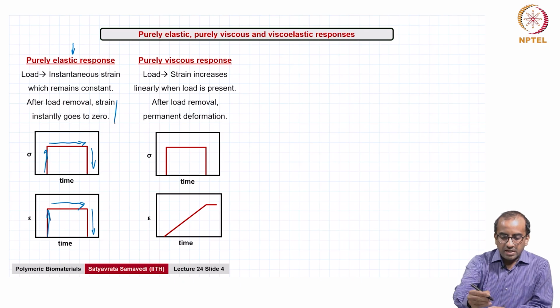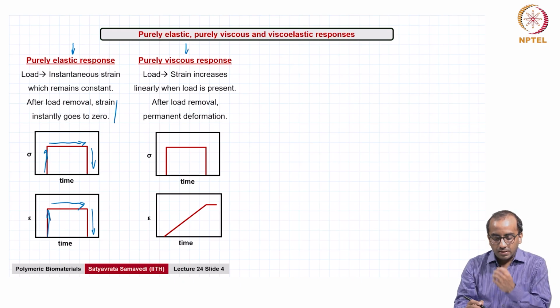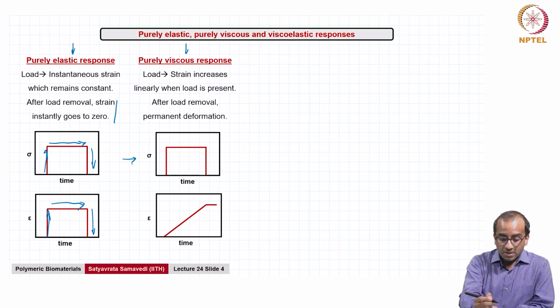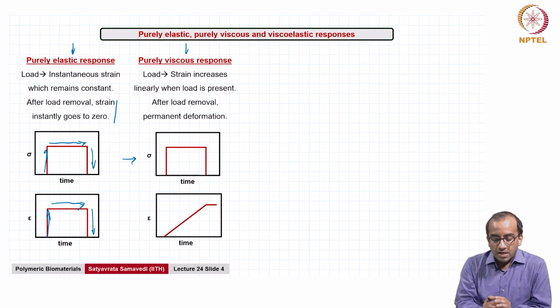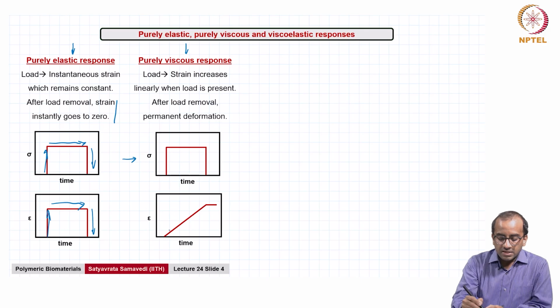Now in contrast, you have a purely viscous response as shown here. The same type of load is applied to a purely viscous fluid, and as long as the load continues to be applied, the deformation or the strain increases linearly with time.